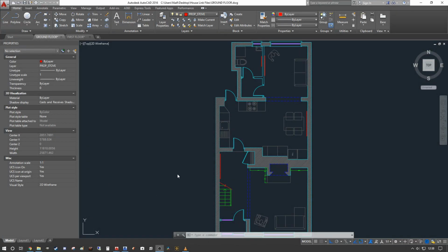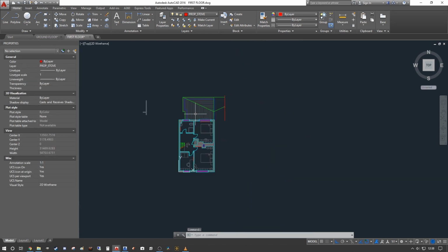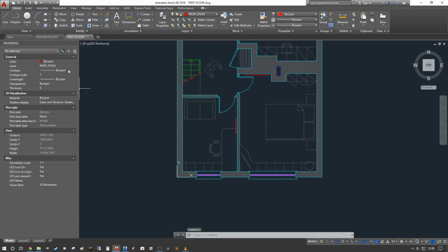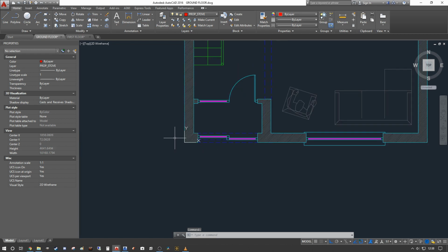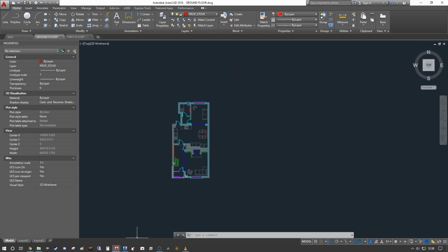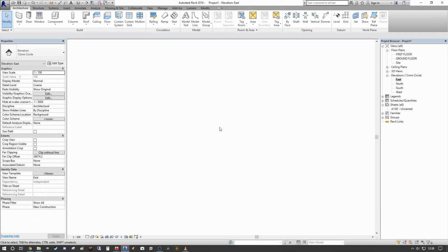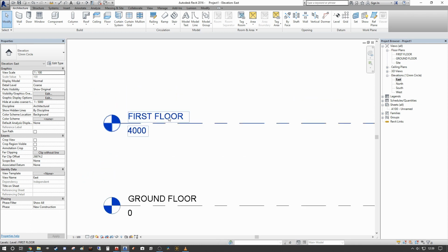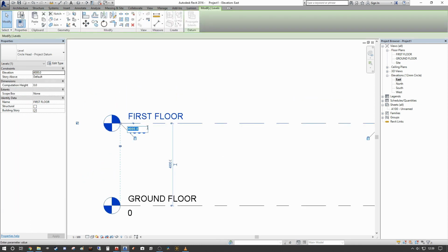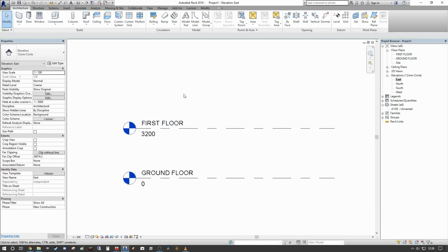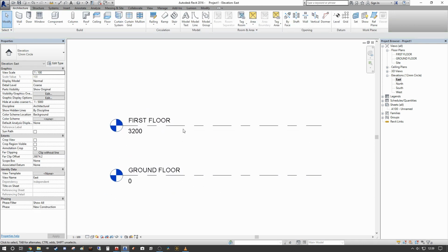Hi guys, so following on from where we left off, as you can see, we have our ground floor and now our first floor plans placed with the origin consistent, and both corners that we know as the building rises up through the levels don't change. Okay, so we're next going to go into our blank Revit file that we have here, and we have two existing levels set up. That's maybe a little bit high, so we're going to save that to 200. So you can see we have our ground floor and our first floor, or our level 1 and level 2, depending on where you are.